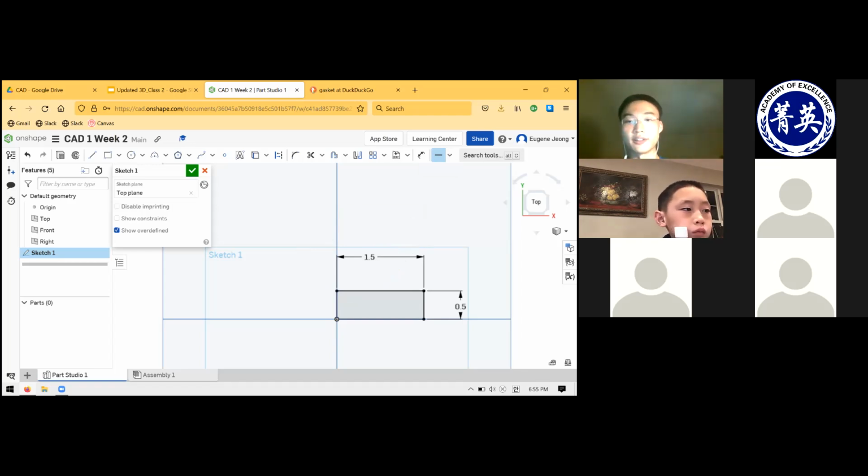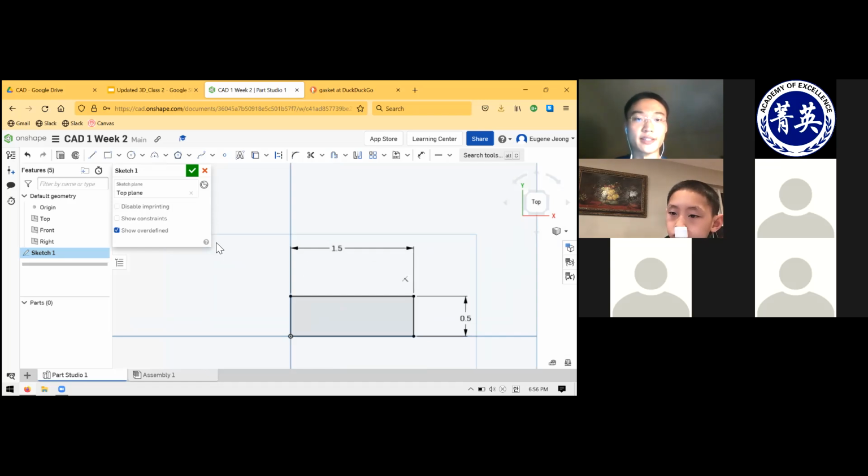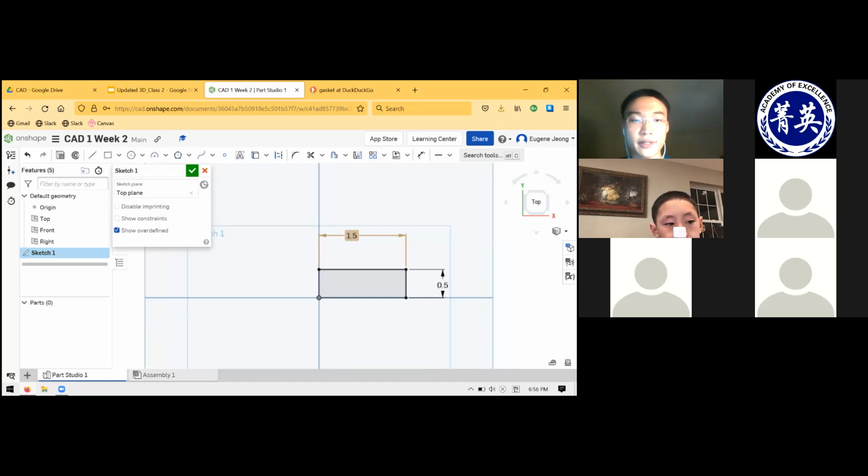And now, finally, you can see that my entire sketch has turned black. And what does that mean? If I try to grab the points like I did before and drag them around, nothing can move. I can't change anything. And what this means is that finally, I've fully dimensioned the sketch. Given the rules that I've placed upon this drawing, given this set of relations, the parallel, the perpendicular, this horizontal, and the two dimensions, all of those combined make it so that there's no other possible configuration that this sketch could exist in.